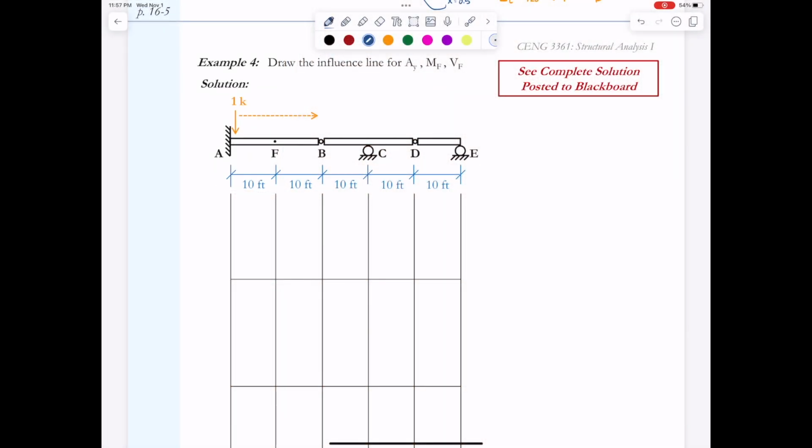All right, so now we just want to plot that displaced structure as we saw it happen. So again, I'll come into point A, and I'm going to release the reaction. I'm going to shift it up a value of 1. I always like to draw in what my structure looks like, where it's locked in. You can think at the roller supports, it has to be locked in at 0. I shift that up 1. Again, because of that fixed connection, it can't bend along that segment. And so we have basically a straight line heading all the way out. And then once we get to the hinge, it starts to bend. It passes through 0 at the roller. It then would have to remain a straight segment all the way to point D. And again, we're looking at rigid body rotation here. We can use similar triangles to solve the values.